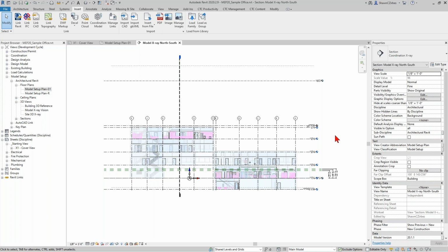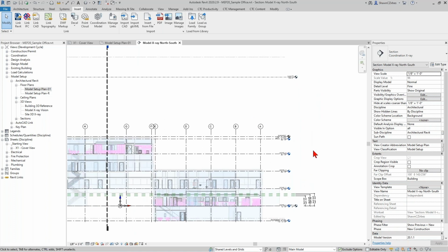But what I've found is that a lot of our customers tend to have somewhat shorter buildings. They're not using 10 levels, and they do a lot of subtraction style work. We do have a Dynamo routine that comes along with it, but if you're not a Dynamo expert, you don't feel comfortable using that, it can be kind of cumbersome for you to leverage that routine to sort of strip stuff out. And if you have different build versions, it can be kind of frustrating. So we like to do an additive workflow instead of a subtractive workflow. Since pretty much every project I've ever worked on has at least a ground floor and a roof level, I leave those 2, and then anything else inside of here is whatever you want to do.